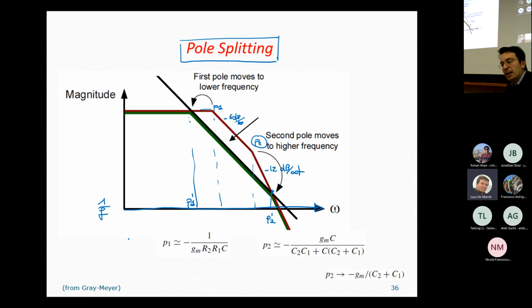Okay, so if we have this condition that we will force as designers by tuning properly the circuit parameters, this equation can be simplified in this way. We can replace this arctangent with 90 degrees. Then we will have the arctangent of omega null over P2 plus 5.7 degrees here.